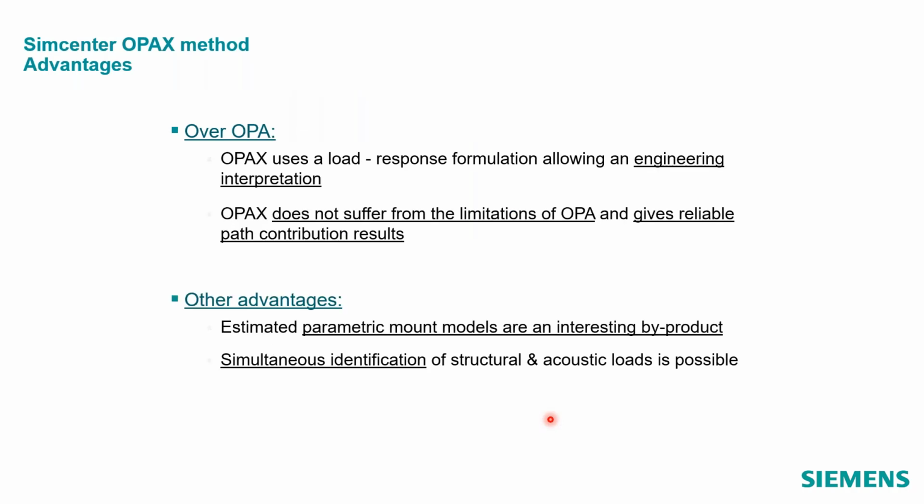Advantages over operational path analysis. OPACS uses a load response formulation. So it's using force-based transfer functions or volume velocity-based transfer functions. It doesn't have the limitations of OPA and gives reliable path contributions. Other advantage, the mount curves are a nice byproduct. And we can also solve for acoustic and structural loading at the same time.